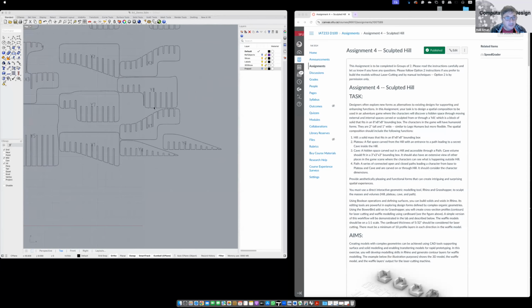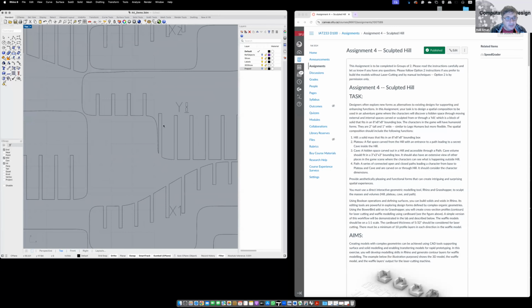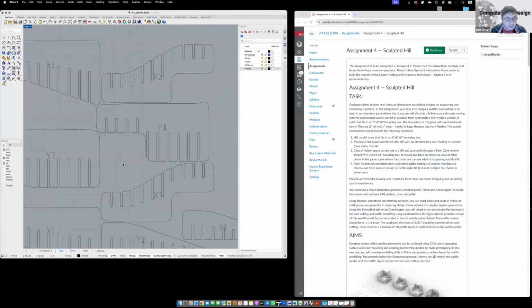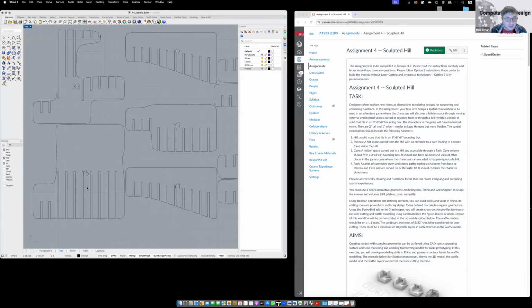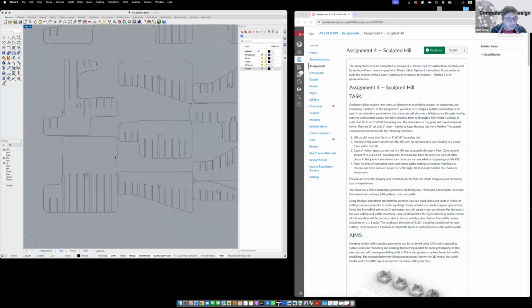You don't want it. And also there's this notch that I want to get rid of. And also some leftover dots here to define the orientation. I don't have that problem. And I don't want to make the laser cutter busy with this. So let's start first with the text. How do you fix the text? In order not to select and by mistake delete profiles, I'm going to come to the slices and lock it so that nothing happens to them.